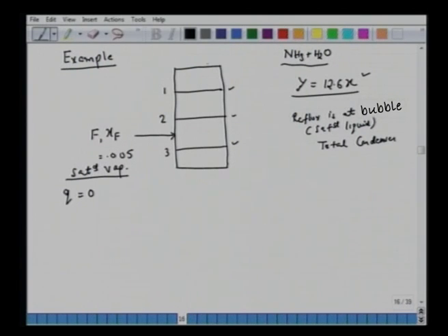Essentially, the vapor from the top plate comes to a total condenser. We have the top product with flow rate D and composition XT, and the reflux with composition X0 and flow rate L0. This is Y1, and the vapor flow rate is G. We have the same nomenclature. This is X0, we have L0 equal to L, vapor leaving from here, liquid dropping from here with composition X1, and this is top plate 1, so this is Y1, and this would be Y2.